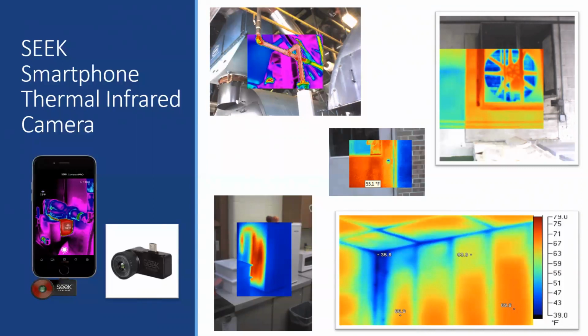In these photos, you can see that we have used the infrared camera to look at pipe insulation or the lack thereof. We can see air infiltration through a fan that wasn't properly sealed. There is an exterior door that's actually an interior door. It is leaking all that air. We also have a fridge that has equipment around it, and that equipment is overheating it on the side, which means your fridge is working harder to maintain the food and such inside to be cooler.